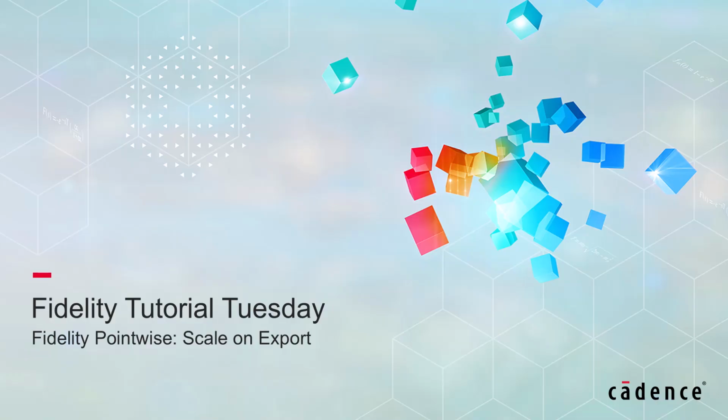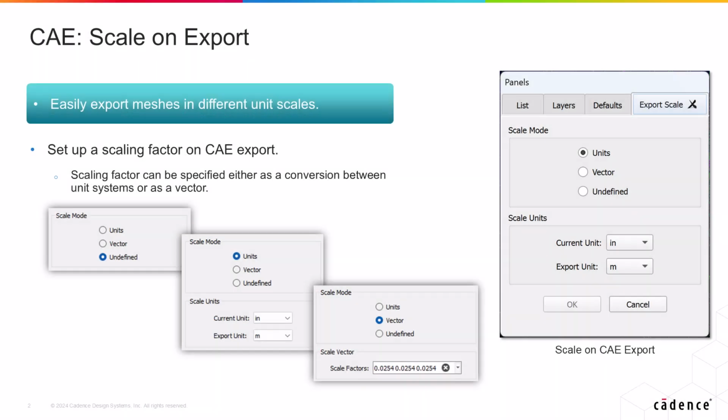Today, we're going to talk about the new Scale on Export option in Fidelity Pointwise. Starting with the Fidelity Pointwise 2025.1 release, we now have a new command under the CAE menu called Set Export Scale. As the name would suggest, this tool allows you to set up a scaling recipe for your CAE solver mesh export. In this way, anytime you're ready to export your mesh to your designated CAE solver format, Fidelity Pointwise will automatically scale your mesh from its current units to your desired units.